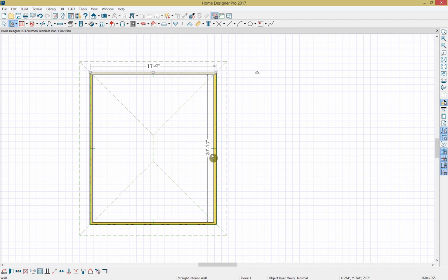So let's take a look at what we've designed so far. We have different camera options to choose from. So let's go up to our default tools and we can select between full and floor cameras. This will get us an idea of working on the inside of our home. We can zoom in depth a little bit more easily here. We also have a perspective full overview. This will keep the roof on our structure, a dollhouse view, which will basically be a bird's eye view into our plan, and then a perspective framing overview, which will show the framing of the plan.